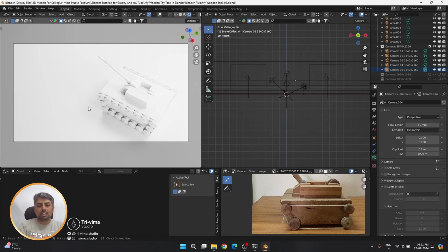So to prevent that, you have to do those changes in solid view and keep saving in minimum intervals. Keep incremental saving at minimum intervals, gaps like 5 minutes, 10 minutes. It's your choice. Whatever you do, always remember, make a habit of saving. That is very important.